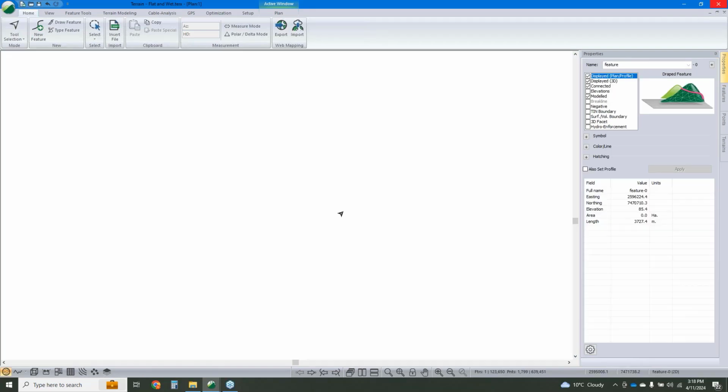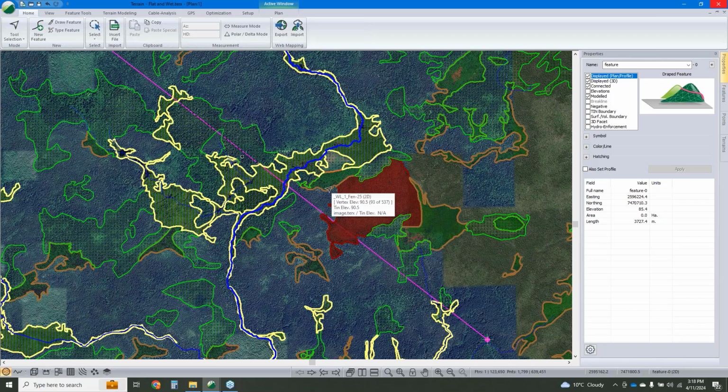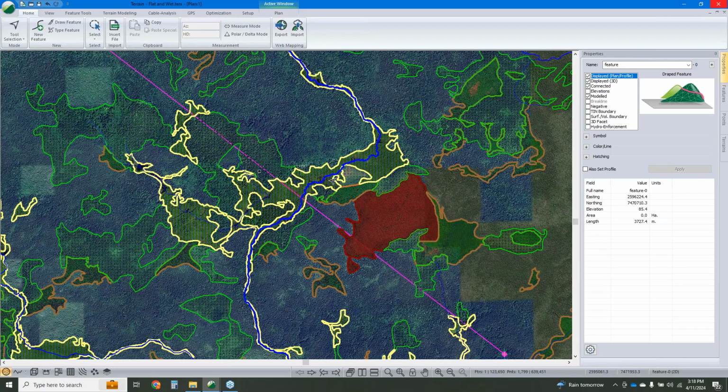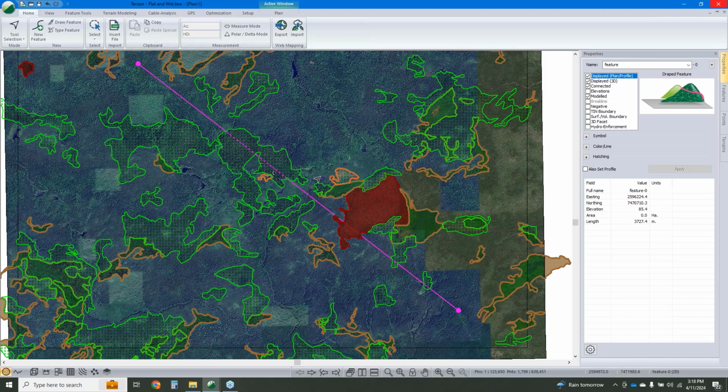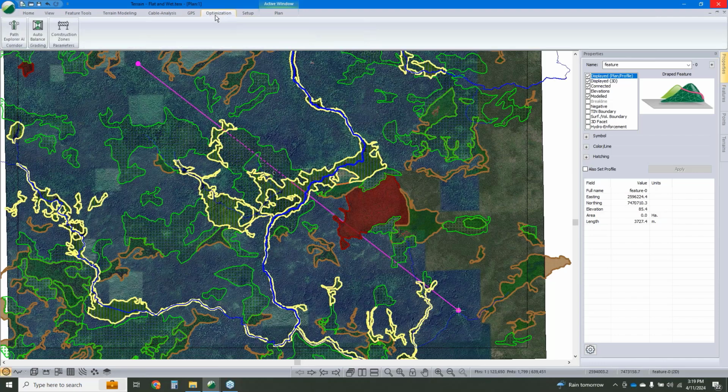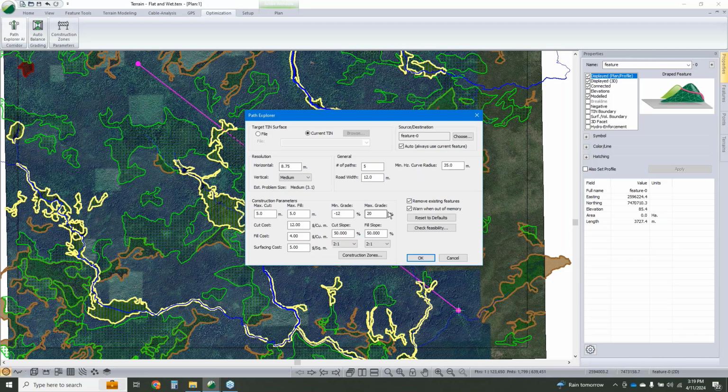So we are going to account for all this by setting up our defaults with that same UI that I used before, but we're going to include the extra with construction zones. So, optimization tab. We could click construction zones to get to where we're going to go, but I'm going to do my defaults first in this portion of the UI.